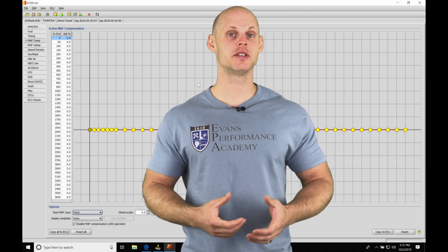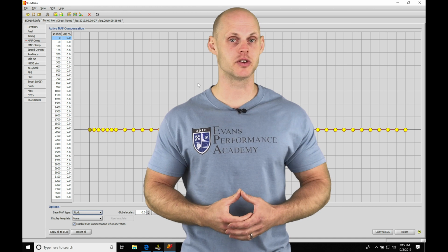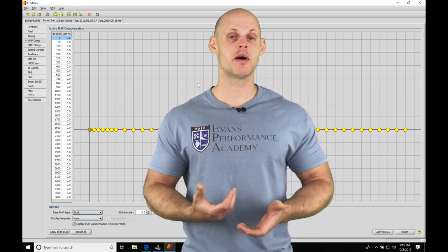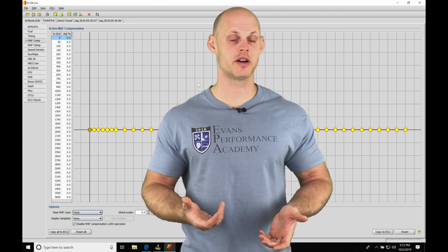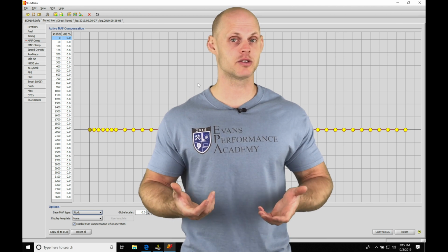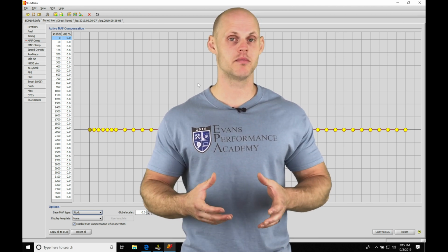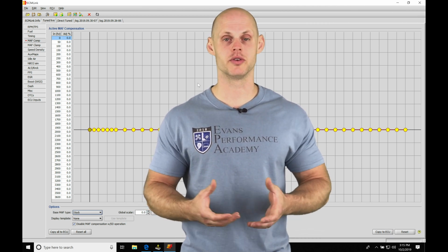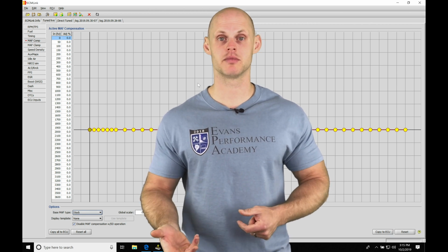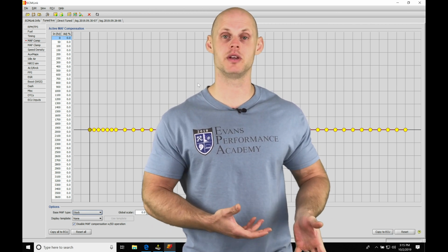Okay, so let's jump into this video and talk about our MAF compensation feature in our ECM Link software. MAF compensation is going to allow us to correct for any kind of differences in our air mass reporting. So we have our OEM, let's say our mass airflow sensor installed on our intake, and we install a different intake that can flow a different amount of air into the engine. We need to correct for that.